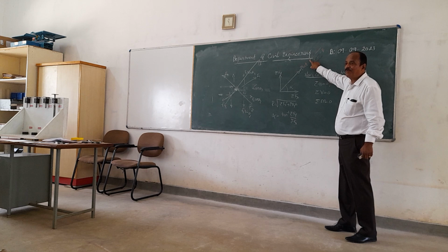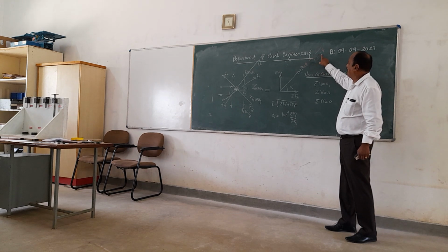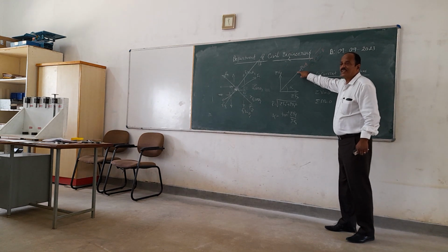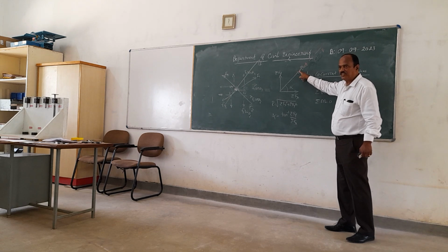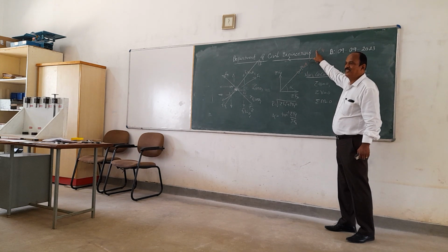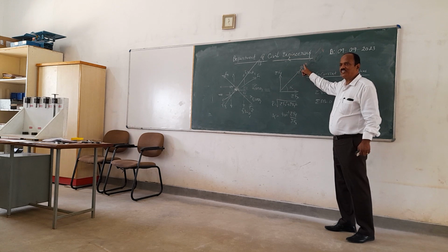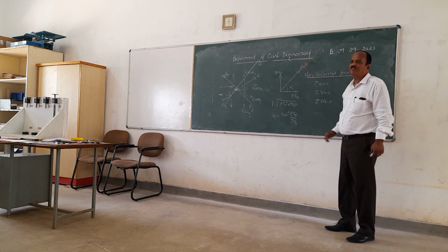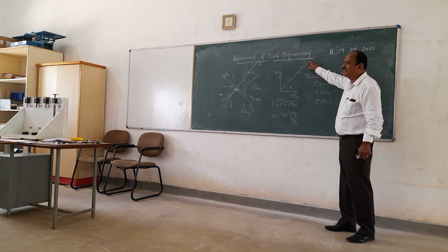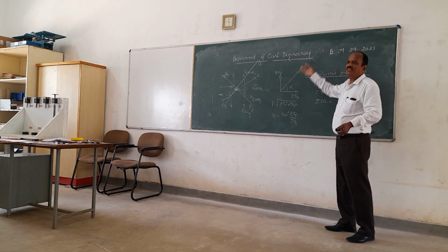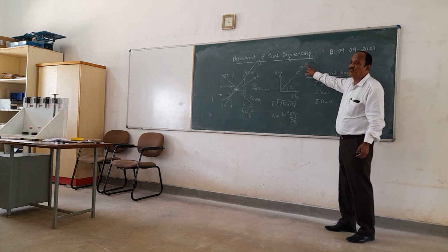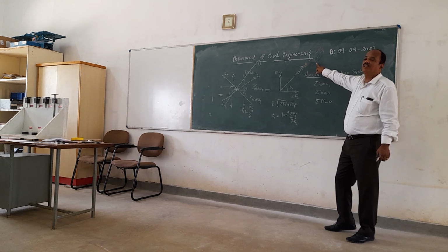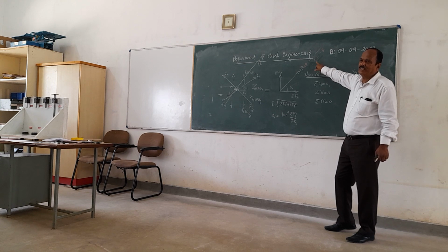The single force we add should have the same magnitude. It should act along the same line of action, but opposite to the direction of the resultant. Say the resultant is 10 kN. We are going to add a force of 10 kN along the same line of action, but opposite in direction. That added single force we call the equilibrant. With this force added, what's the net value in that particular direction? It will be equal to 0. The system will be in equilibrium.